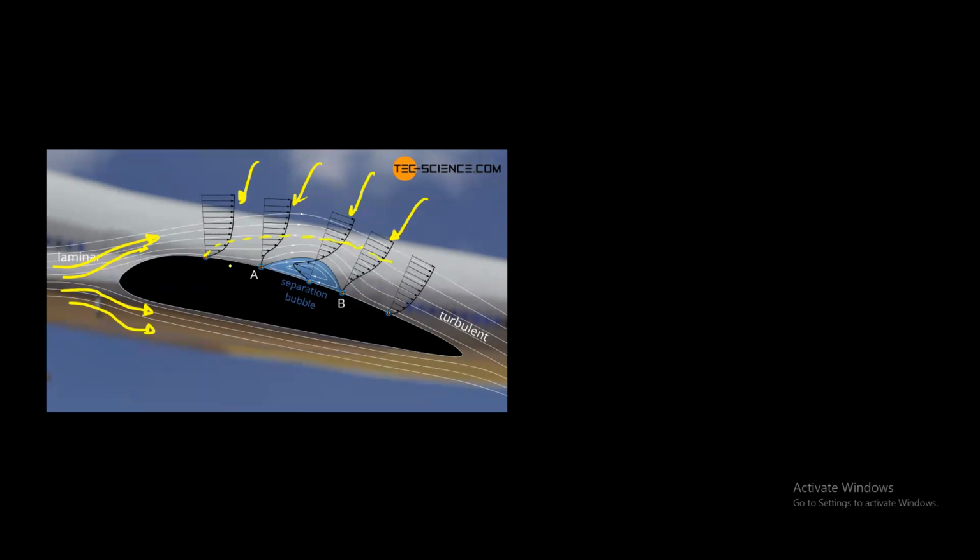Because of this, it creates two types of forces. One is called a drag force, and the second is the lift force. To determine this drag and lift, we need to study the concept of boundary layer. Drag means what? Because of air, this airflow will create a force in the flow direction. This force will try to push the wing of the aeroplane in the direction of the airflow. So this is called drag.